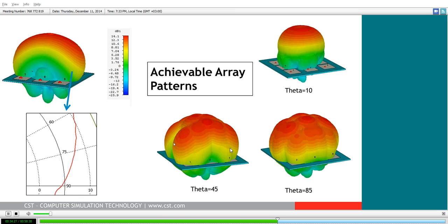This is really only giving you the plus minus 180 degree, or the top hemisphere of your spherical radiation pattern. So in the eventual device, we'll need a pair of these, one on top and one on bottom, to get the full spherical coverage that we want from our device. If we look at a single azimuthal angle to get a so-called cut of this performance, we can see that really we're only hitting our 12 dB target out to about 60 degrees in this case before we're degrading below that gain.